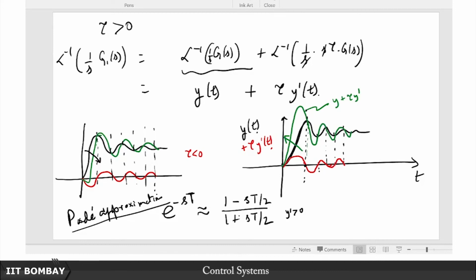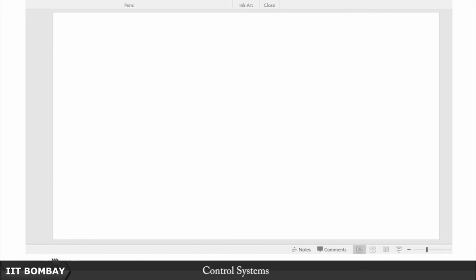So you see, not surprisingly, this has a right half plane 0, of course this T is assumed to be positive, and we see that whenever you have a right half plane 0, you have this sort of an undershoot. We saw this as a matter of fact even with the first order step response, if you recall, right. So that is an important thing. To finally conclude our discussions on these effects of additional poles and zeros, let us quickly summarize it in the form of this particular picture to leave you with.